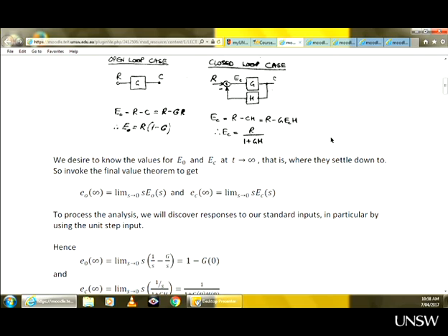It would be an interesting exercise to create a linear model of a bootstrap system. We actually have a thesis student simulating the whole cabin environment in MATLAB. We could divide this into linear blocks. This G has the compressor, heat exchanger, and turbine, and whatever else happens on the way to the cabin. H is the transfer function of the temperature sensor.